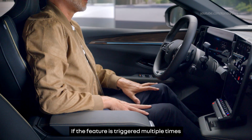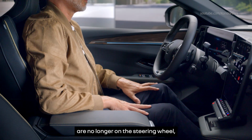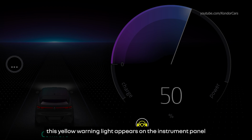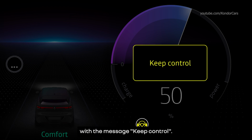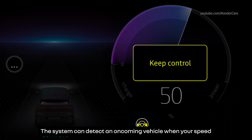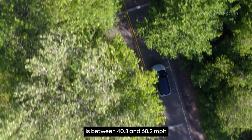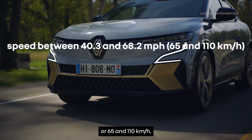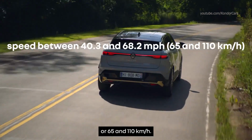If the feature is triggered multiple times due to an approaching roadside and it detects that your hands are no longer on the steering wheel, this yellow warning light appears on the instrument panel with the message "Keep Control." The system can detect an oncoming vehicle when your speed is between 40.3 and 68.2 miles per hour, or 65 and 110 kilometers per hour.